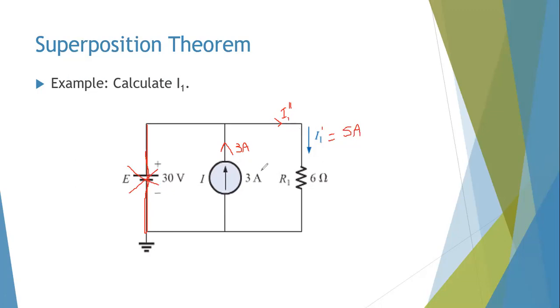It's a very simple question, but many students actually fall into the trick here. If you have this current here, which has to split into 2 paths, it's very logical that it goes along the path with lowest resistance, so the 3 ampere will fully go across this path here. Because there's no resistance here, the 3 ampere will simply go here. No current is going to flow here, because it's a short circuit, there's no resistance to the path of current.